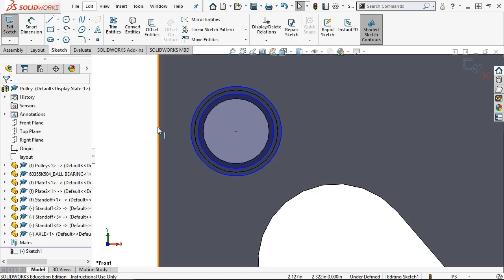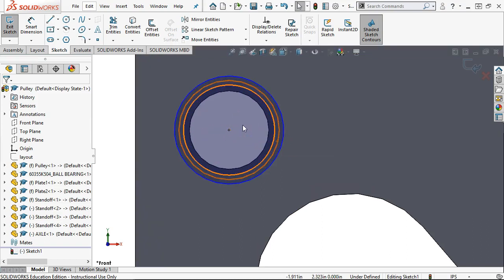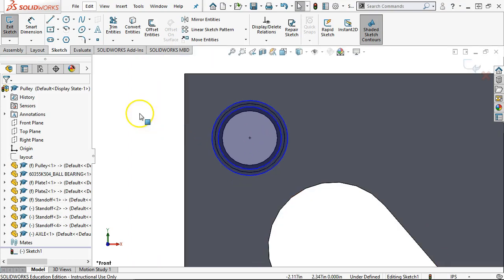Whether it's a thousandth, a couple tenths, or exactly the same, we're always going to see that little bit of fluctuation, a little variation. So what we're trying to do with the positional tolerance is tell it that it has enough room that this is going to be functional in a lot of cases, not any tighter than we need to make it, not any looser to affect the functionality of the part.